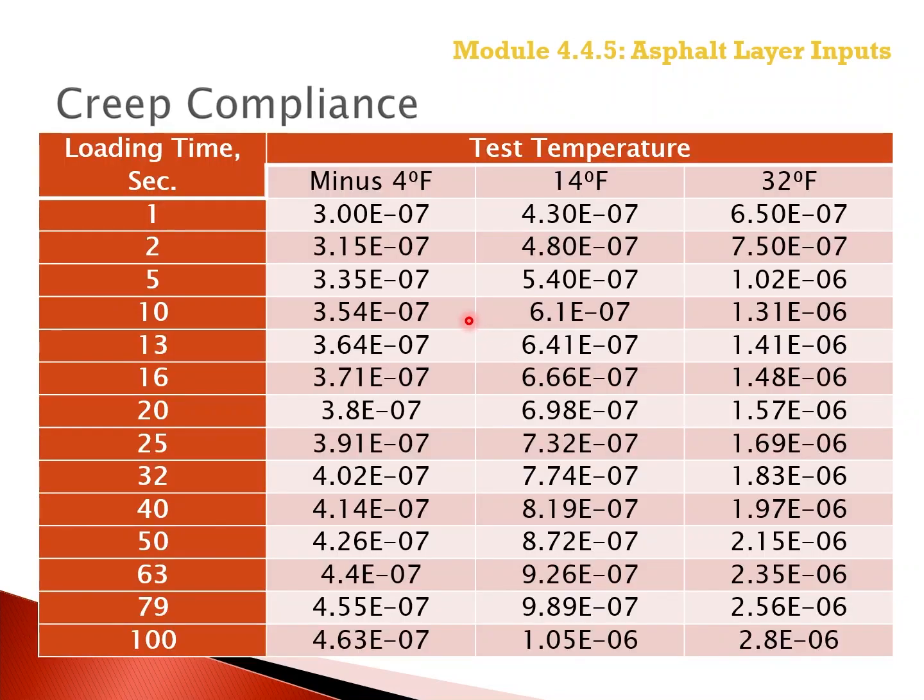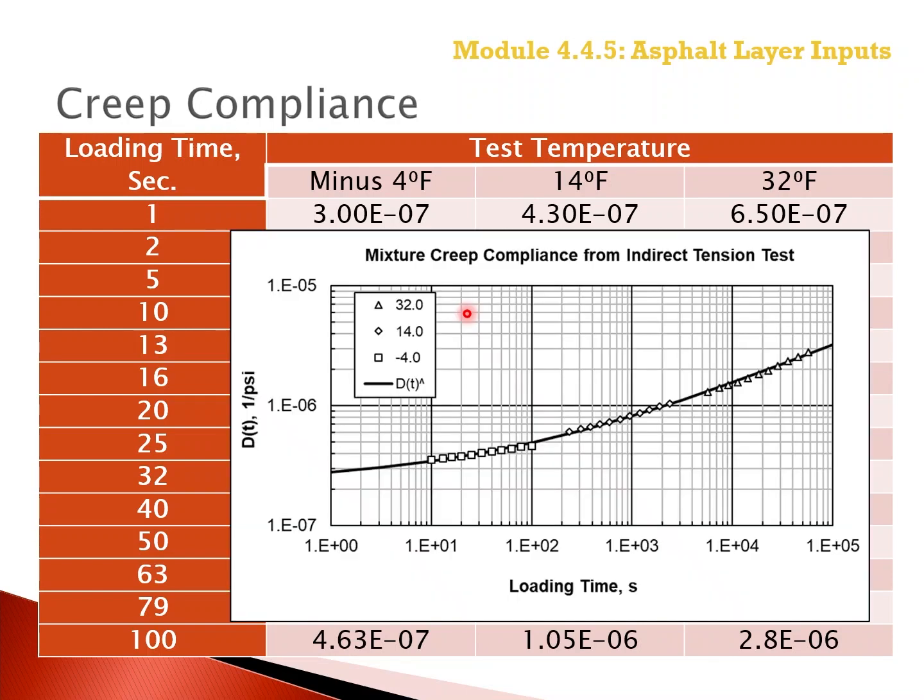The table shown on this slide is an example of the creep compliance values measured at the different test temperatures and loading times as defined in AASHTO T322. The PMED software takes the creep compliance values that are entered in the software and creates the creep compliance master curve. The designer does not need to calculate the master curve unless they want to in evaluating the test or measured values themselves.